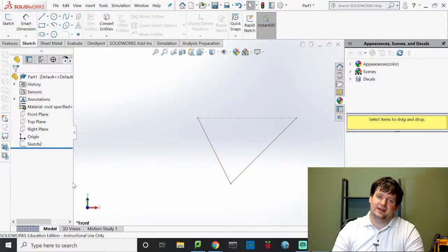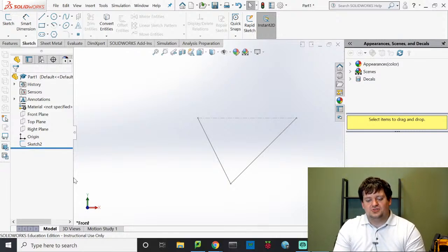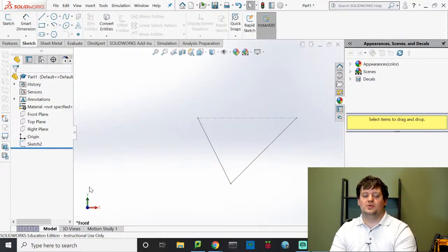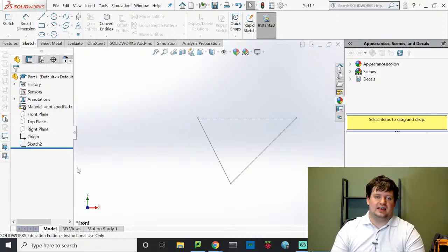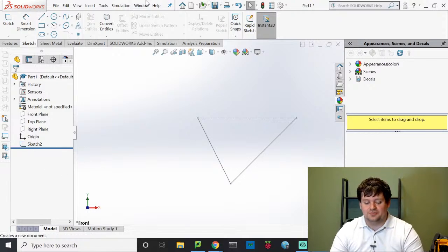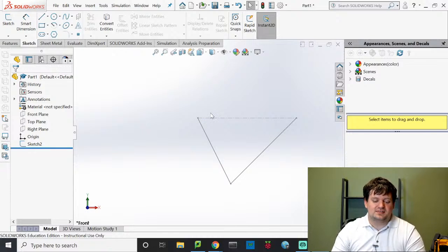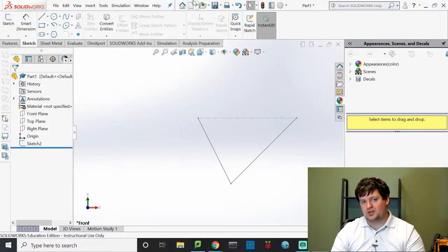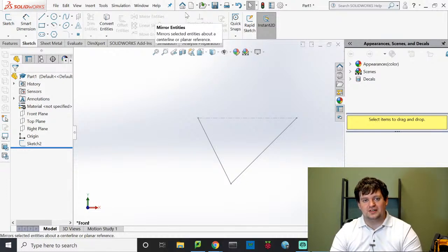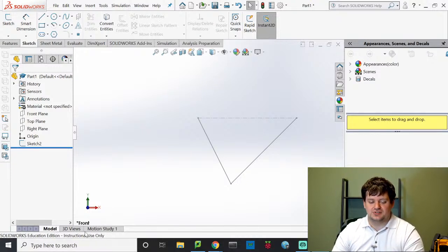If you do over constrain it, you will create some issues if you put in too many dimensions or if you put in too many constraints. SolidWorks will say, I can't build it with all of the dimensions and constraints you made because some of them are driving and some of them are driven. So it's just best, in my personal experience, I like using constraints more than I like using dimensions. But that's just because if you use a constraint, you have to go back and redesign it. It's easier for me to adjust the constraint than it is to go back and try to neatly rebuild something with dimensions. And in general, that's the case. When it comes to it, constraints are your best friend in SolidWorks.